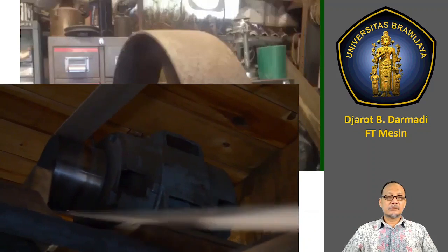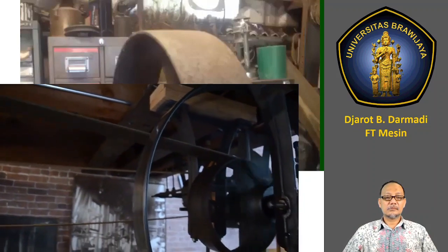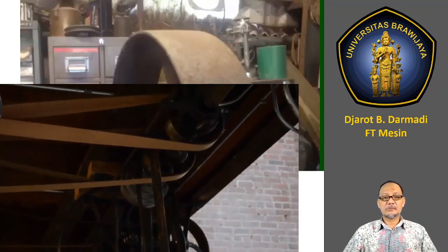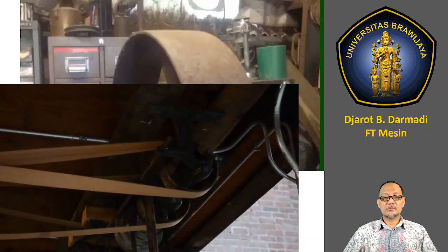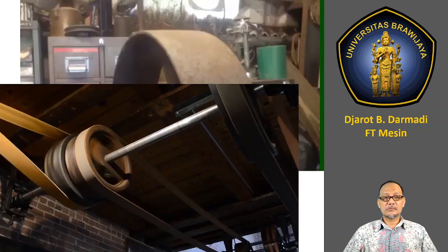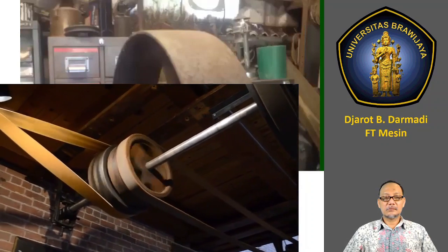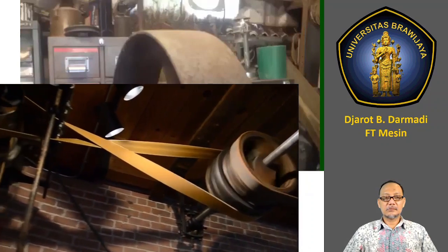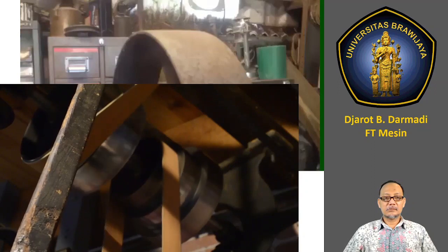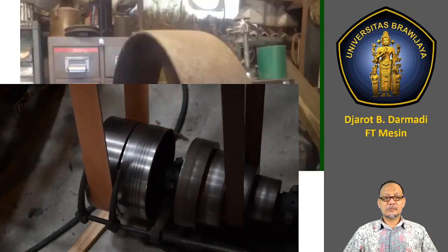A belt is looped at one end around a pulley driven by the motor, and at the other end around a pulley fastened to a shaft, causing the shaft to rotate. Belts looped around other pulleys fastened to the shaft then transfer that rotation to other shafts or directly to machines. An open belt connecting 2 pulleys causes the pulleys to rotate in the same direction, but a belt can also be made to form a crossed loop to turn the pulleys in opposite directions. Power from the line shafts can be engaged to the machines by shifting the belt from a loose pulley or idler turning freely on the shaft to the drive pulley fastened tightly and rotating with the shaft.